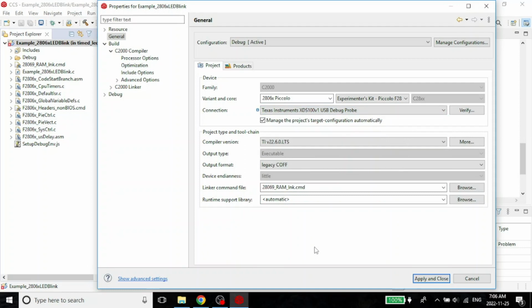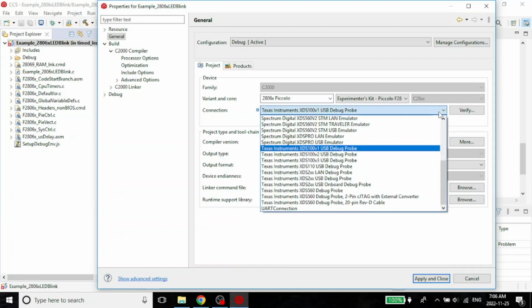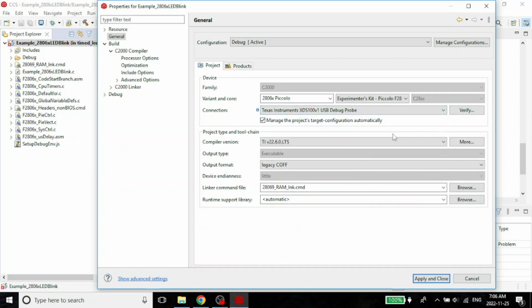When you get your microcontroller kit, inside the package there will be a document. It's more like a glossy paper, but that glossy paper will show you some details of what is available and what is not, right? And in one part it does show you which version of the USB debug board can be used with the kit. But in any case, make sure that if one of them doesn't work, try the other and click on this verify to make sure that your connection is successful.